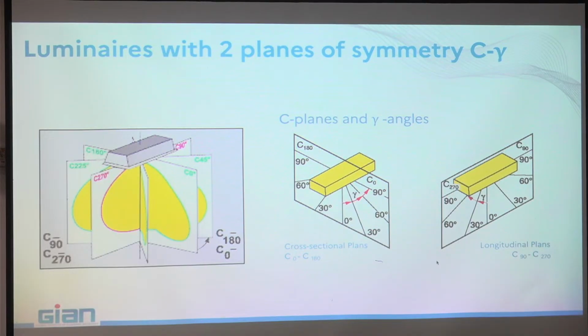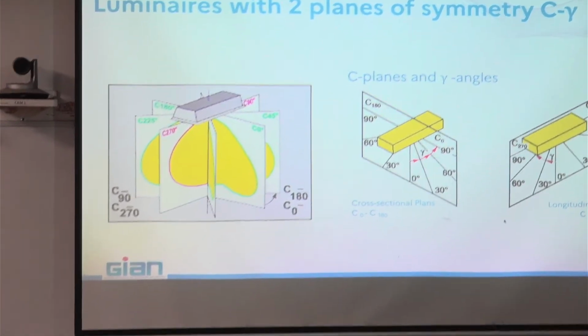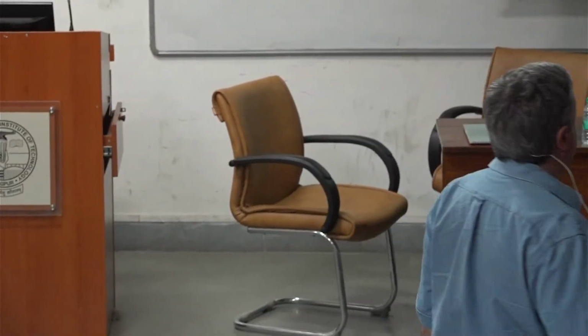I don't know which one, but say if the maximum of the fixture is at 30 degrees, the manufacturer has to give you the C30 and the opposite plane in order to be able to make your calculations better, because your fixture is sending more light to a given position. We'll see some examples after.